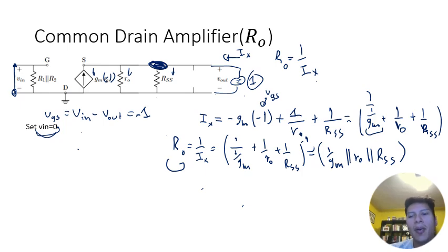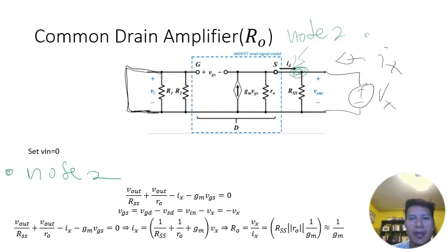And now we're going to look at the input resistance. But before we do, here I do it in a more clean fashion. And so here I plug in my Vx, which is equal to 1 volt typically, so that I get that VGS is equal to Vin minus Vout, which is Vx or 1 volt.